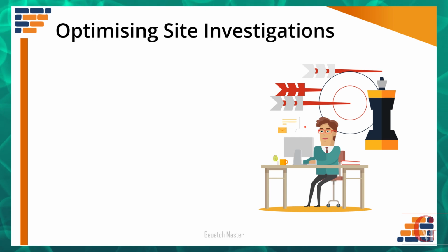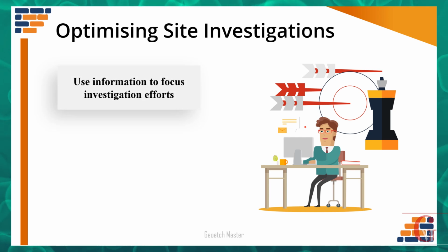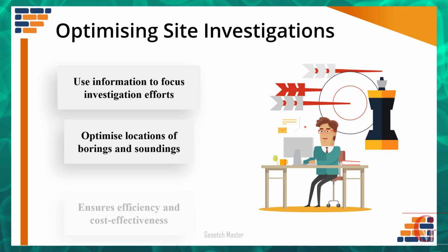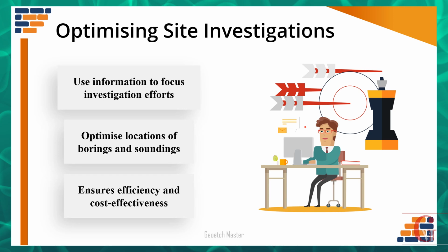Once we have this initial picture of what's going on, we can use the information to decide where we should focus our efforts. This means we can optimize the locations of our subsequent borings and soundings, making the whole site investigation much more efficient and cost-effective. Imagine this: if we did not use geophysics to look at the big picture first, we would be doing investigations blindly. But with geophysics, we are more confident that we are investigating the right areas.